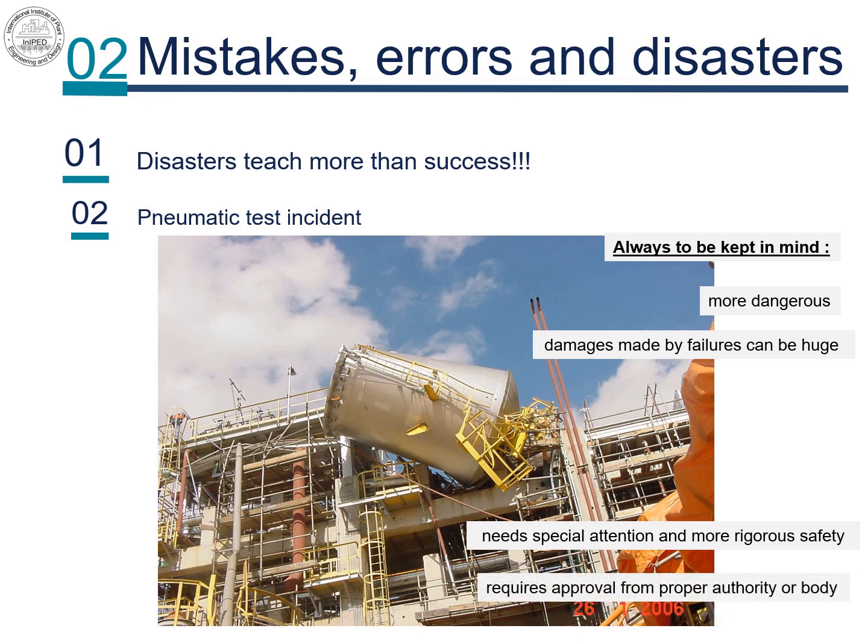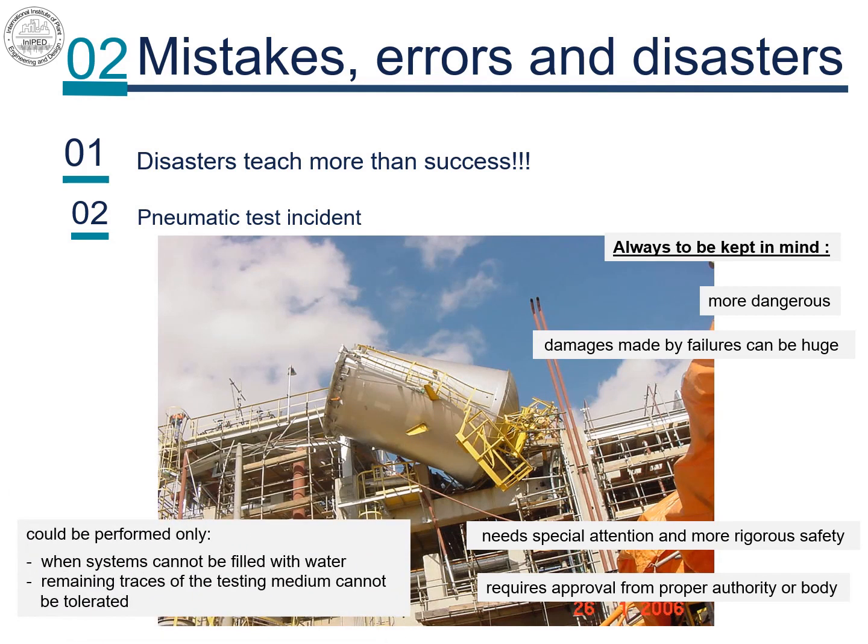Pneumatic tests could be performed only when at least one of the following conditions exists. A. When the systems are designed in such a way that they cannot be filled with water. B. When the systems are such that they are to be used in services where remaining traces of the testing medium cannot be tolerated.